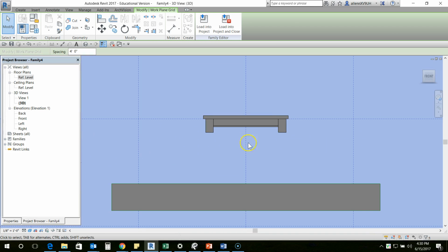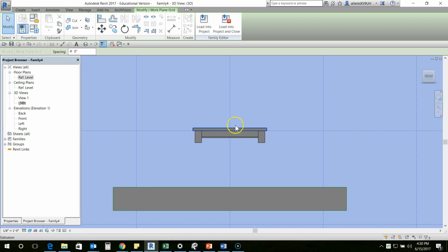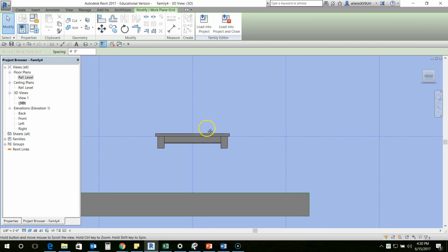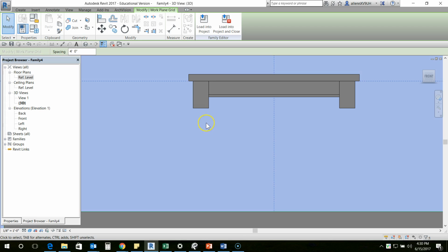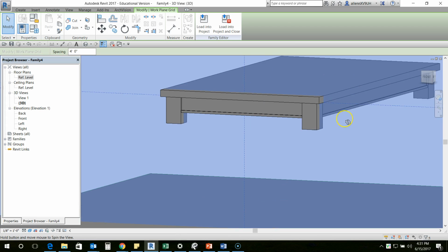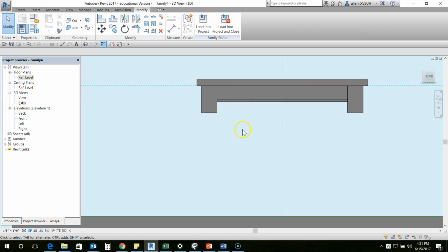Okay, you could also do the same thing here just by going to one of the elevations. And then there you would have to set the viewport to be, the work plane to be the table front. You make that the active one again. Okay, but since we've already done that, here we can do everything that we would be able to in an elevation, only it's a little bit easier to see in 3D view. I can keep going like this and then going back to the front view to check my progress.